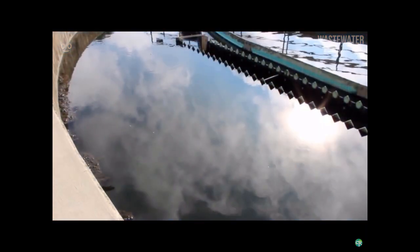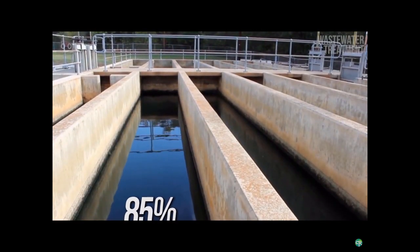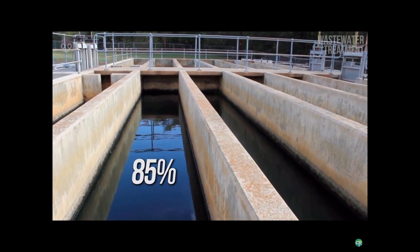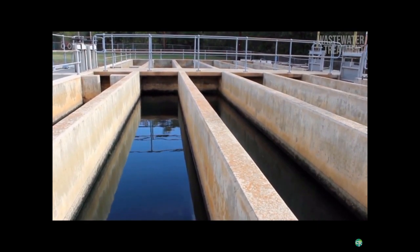Water flows out of secondary clarifiers over a nearly identical weir wall to the primary clarifiers and moves on to the disinfection process. At this point, 85% of all organic matter is removed from the water, and the effluent should be safe to drink in most cases, although you probably wouldn't want to.